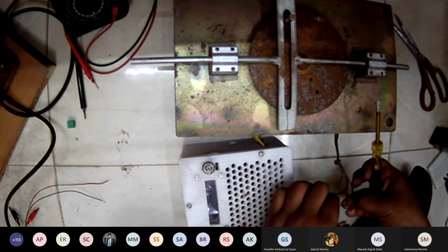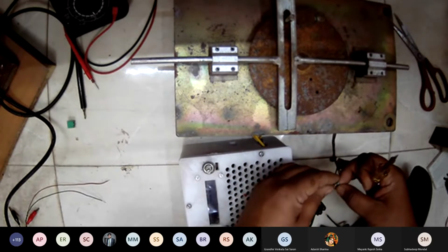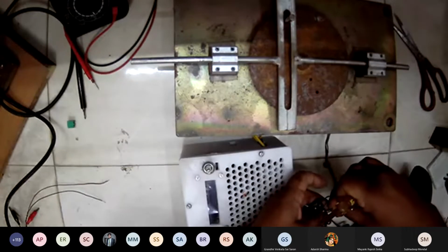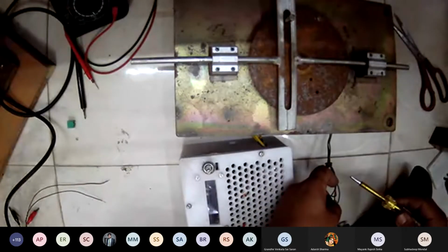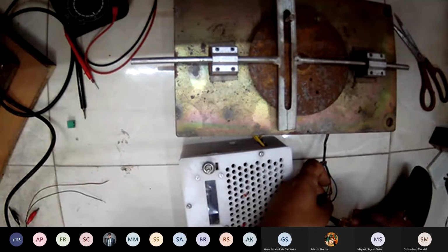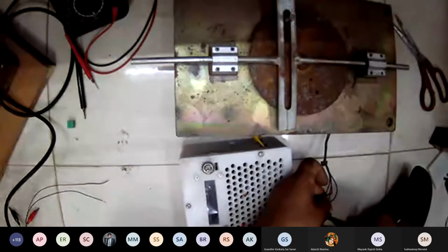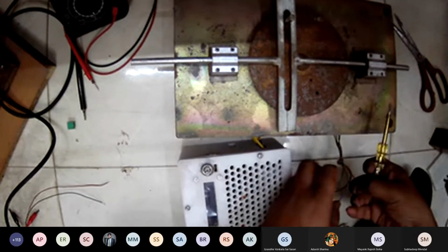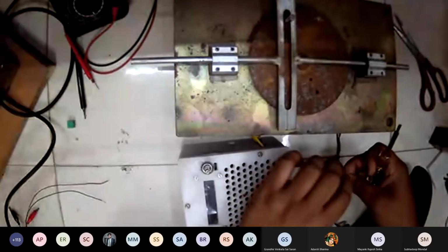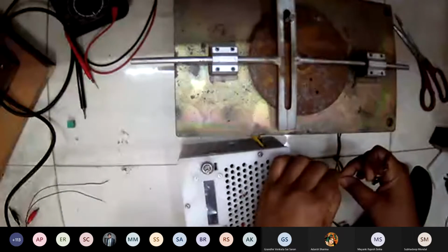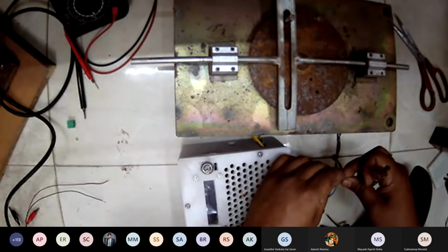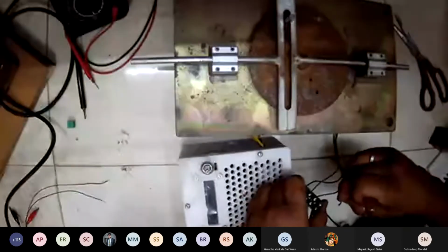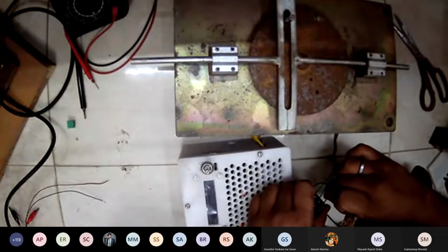So in 3D printers, in CNC machines, such kinds of stepper motors are used, and you can connect what is known as an encoder to the back of the stepper motor, so that if you feel your application requires a very high amount of torque, there is always that doubt in the back of your head that maybe there will be steps which are missed.